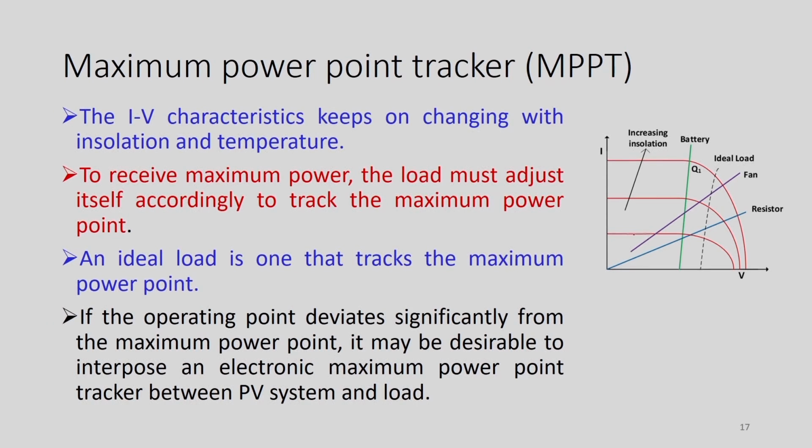Maybe this may be in the morning, say at 10 o'clock, this may be at 11 o'clock, this may be at 1 p.m. So, different curves can be generated at different times. Also, these are dependent on temperature, what we have discussed in the very beginning of this class. This IV characteristic keeps on changing with insolation and temperature.